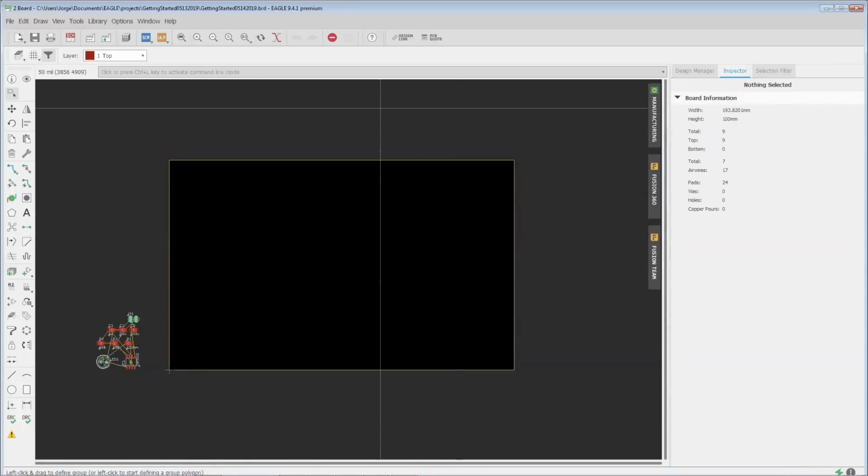So right now I have the premium. In the premium, it just gives you an example size, which is the standard size. That's what it does for the premium. You'll notice that all of our components are here on the left side of the origin. The origin's right here, here's 0, 0. And this is how Eagle will always insert components as you add them to the schematic, because forward and backward annotation is maintained. They'll be appearing in the negative x-axis.